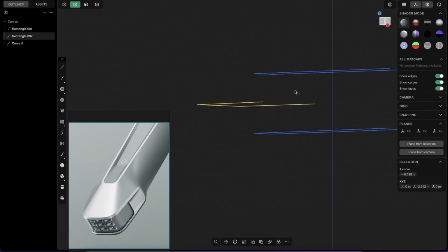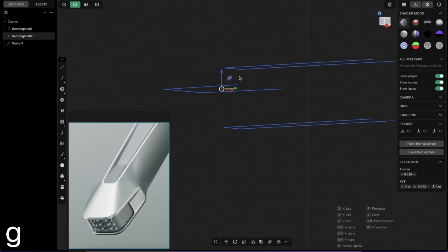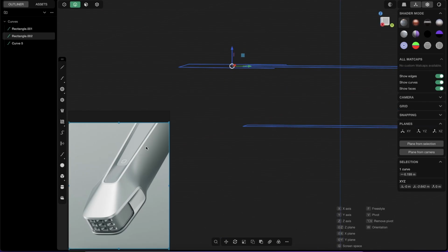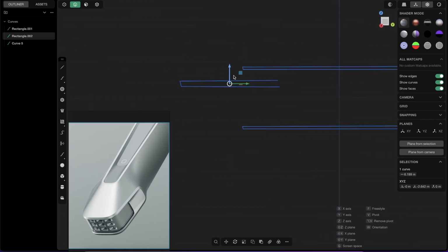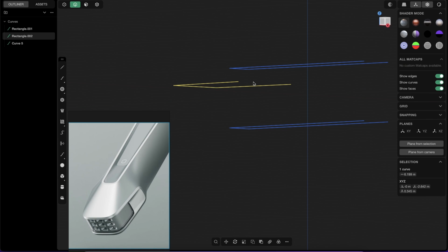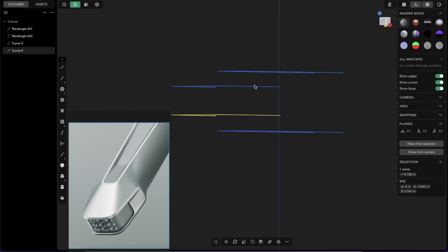And now we have to do the same here. So select that front piece, press G. Bring it a little bit up. Again, very important, don't bring it up to the same level as this edge, because you see we have a little bit of an angle here. So it has to be, again, it's just eyeballing, somewhere in the middle. And again, Alt X and just select that. So you have that situation.